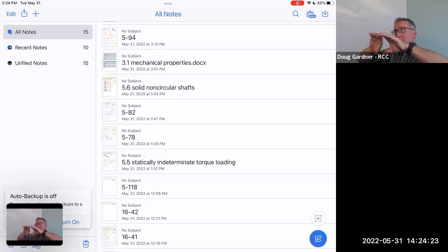If I have a hollow pipe, all that outer material, if I have a certain amount of material like we did a minute ago and I made a hollow pipe, that's actually going to not want to twist nearly as much as if it got way smaller and it was a solid pipe. Because again, it's about distance away. The further it is away from the center, the more it does not want to twist. You're saying replace a denser, smaller pipe with a hollow, bigger one. Exactly, yeah. You weren't here for this, Connor, but that's exactly the same principle.